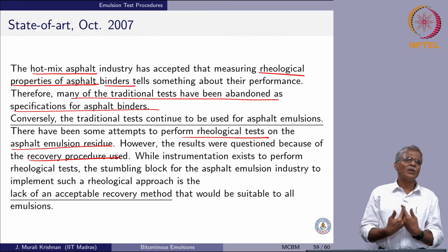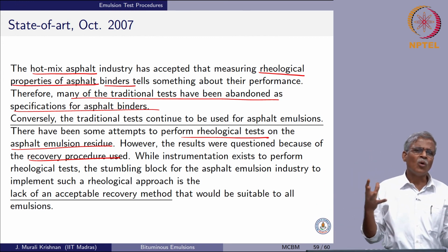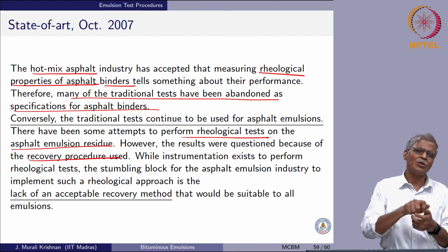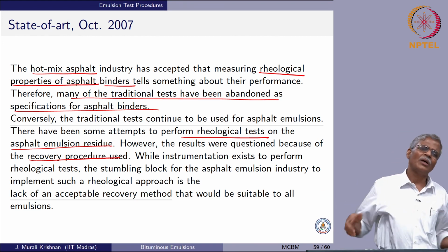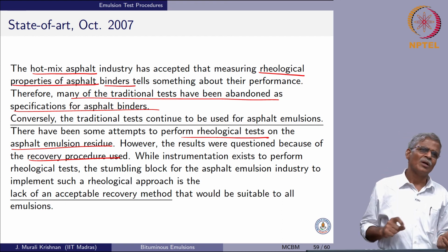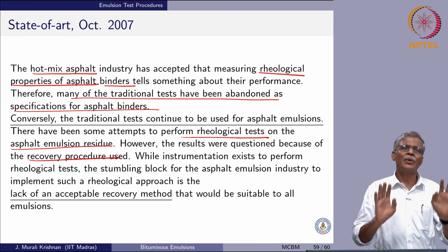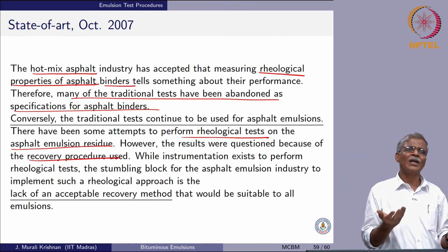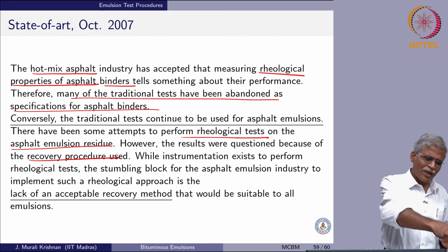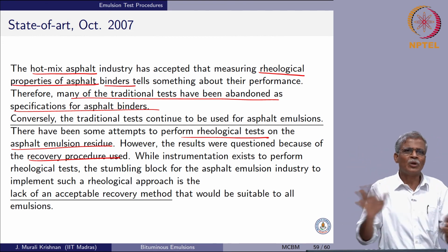What we do in our laboratory at IIT Madras, I just take a silicon mold, a silicon tray, because it is very easy as you can peel the bitumen off. You pour it, let us say for half a centimeter thickness, that much material, and just keep it under the ceiling fan. After 2 days or so, after the water evaporates, you can peel off the bituminous film and then roll it, and you can do the testing.